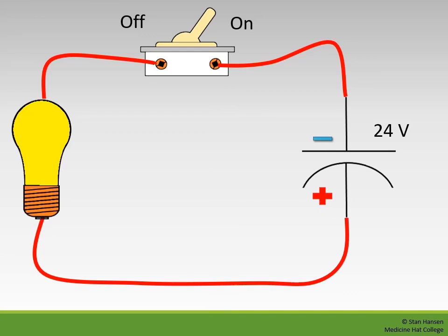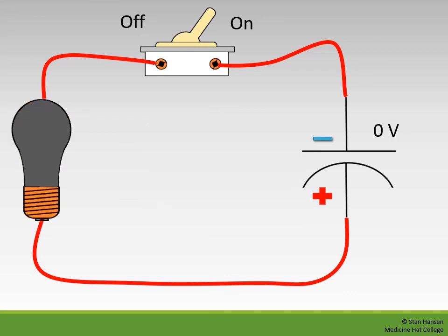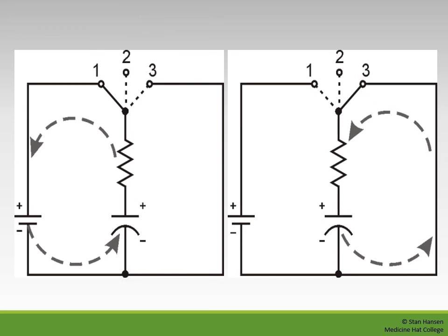The amount of time it takes the capacitor to discharge will depend a lot on the resistance and the capacitance of the circuit. The larger the capacitance, the longer the load is supplied with energy, and the higher the resistance, the slower the electrons are going to travel through the load. Once the capacitor is discharged, then the electrons stop flowing since we have a balance of charge between the two plates. Here is a more typical charging and discharging circuit for a capacitor.